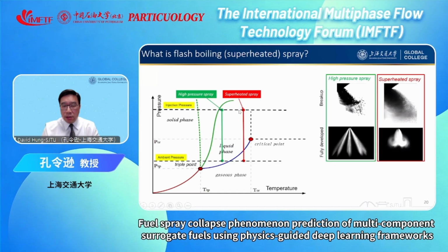the injected initial part is liquid at the ambient phase, but at the initial injection position it is already superheated. You can see that the tip of the spray is obviously very different. And then when it is injected into the atmosphere, which is already in a flash boiling condition, the spray collapses, very compact into the center part and very dense in the middle as well. The same injector spray exposed to different ambient temperature and pressure conditions can exhibit something like that dramatically.